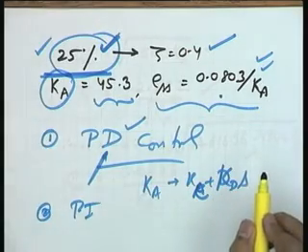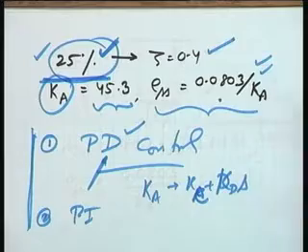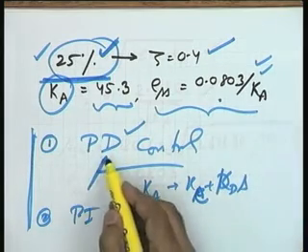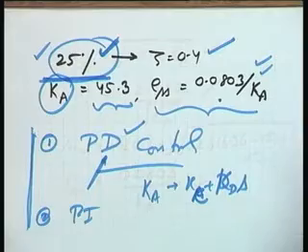The only thing is this, that you have to be cautious in the design that your transient accuracy requirements are also satisfied. And these things cannot come analytically. Graphical methods, the root locus method and the frequency domain methods, very well established methods of control system design, will help you design the values of PD, PI or PID controllers, so that the steady state and transient accuracy requirements are satisfied. And this is the subject of discussion next time. The root locus method we will start with.